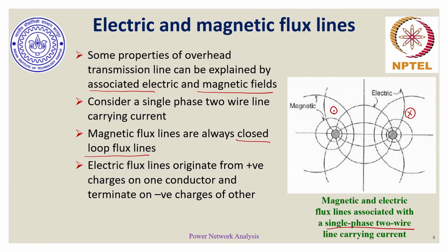So essentially at this instant, the magnetic flux lines are in a counterclockwise direction as shown over here. The same logic, if we apply to the conductor which is carrying current into the plane of the slide, with thumb pointing inside the slide, the fingers curl in a clockwise direction. So the magnetic flux lines are actually in this particular orientation. If I superimpose or combine the magnetic flux lines because of these two current carrying conductors, essentially it appears